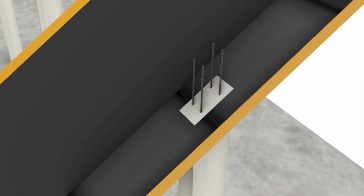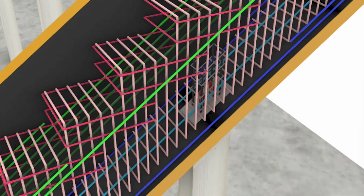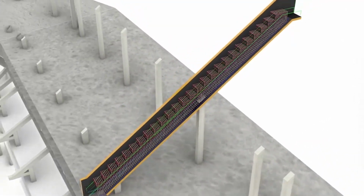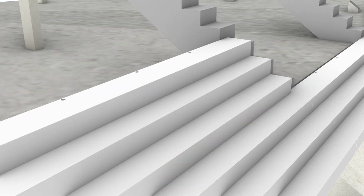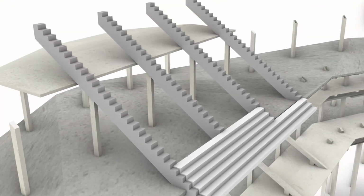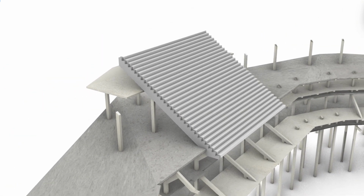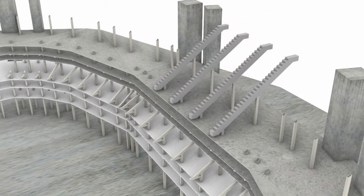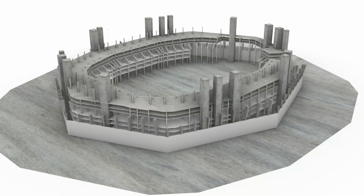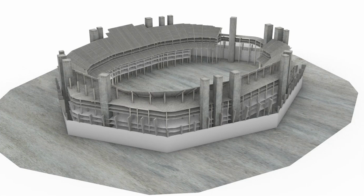This connection is achieved using rebar continuity and dowel rebar techniques with integrated concrete pouring to enhance bonding strength and effectively transfer loads. The grandstands consist of precast seats manufactured off-site. These are lifted by crane and installed between rocker beams, secured using grout pockets to ensure structural stability and precision. The completed rocker beams and grandstands make Mercedes-Benz Stadium a safe and spectator-friendly venue. This stadium, a product of innovative design and meticulous construction, is Atlanta's pride.